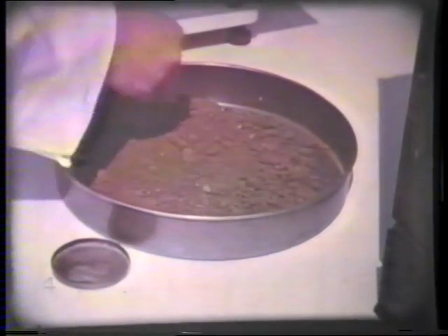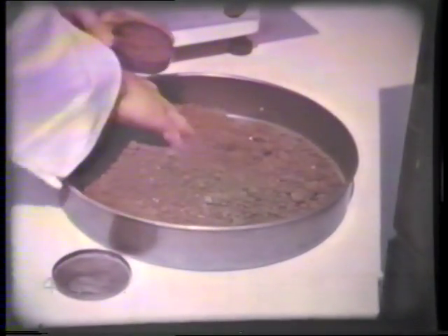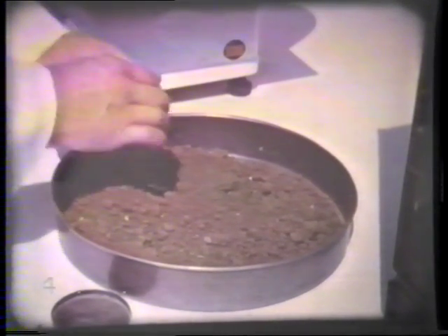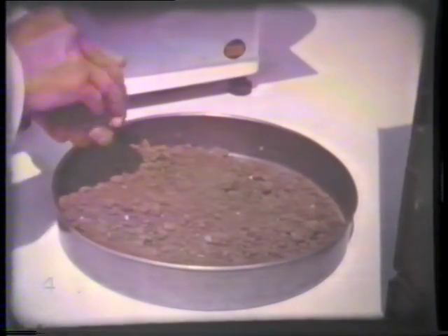In order to calculate the dry density, it is necessary to determine the moisture content of the soil. A small sample of the soil from the hole is taken and weighed. The sample is then dried in an oven controlled at a temperature of 110 degrees centigrade for 24 hours, after which it is re-weighed. The loss in weight of the sample, expressed as a percentage of the dry weight, gives the moisture content. After the measurements of the state of compaction have been completed, the soil is again broken up and prepared for the next tests.